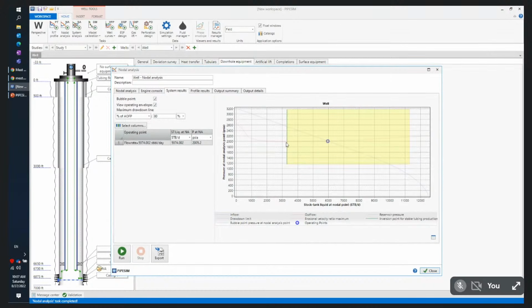So number one, on the left-hand side, this is what you call the inversion point, meaning if you notice that this outflow curve starts going down from the wellhead plus the hydrostatic pressure point. And then as the production increases, the bottom pressure will go down.